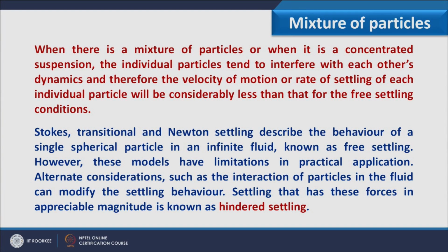The Stokes, transitional and Newton settling expressions, which we derived in part 1 of this lecture, describe the behavior of a single spherical particle in an infinite fluid, and that is why we call it free settling. However, these models have limitations in practical applications. Alternate considerations such as interaction of particles in a fluid can modify the settling behavior. Therefore, settling that has these forces in appreciable magnitude, we call hindered settling.